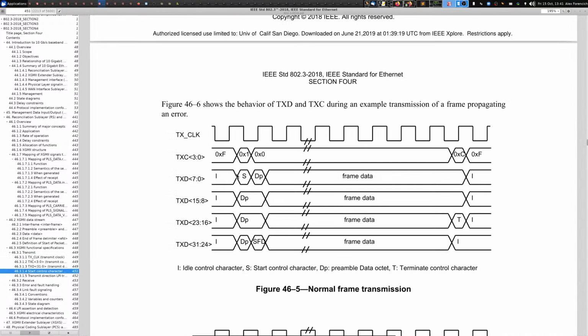You can see on this timing diagram that this is supposed to be a DDR interface where you're transferring data on both clock edges. This is only done this way when you're doing board level connections. If you're working on chip, then you're not going to be doing DDR.